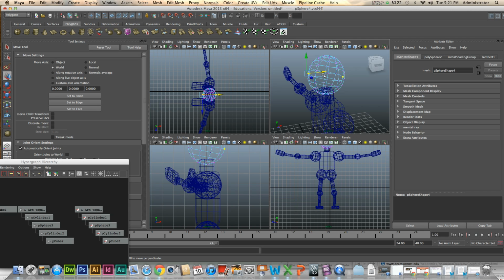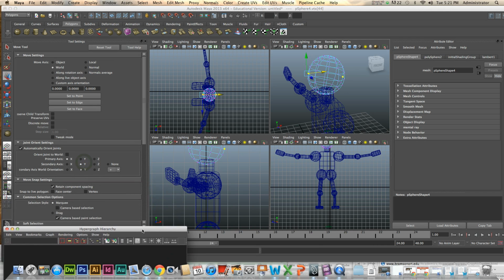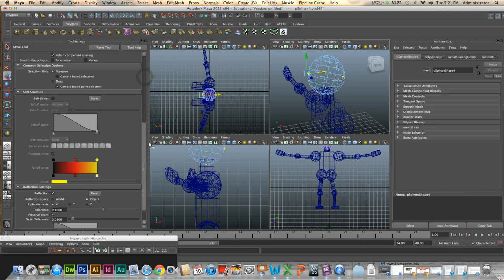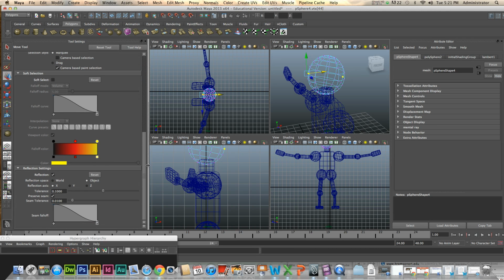And this way you can see that this point is selected. But I'm here to tell you that the reason why this point is selected is not because by mistake I grabbed both of these points. It's because my move tool has something called mirroring on it. And what I'm going to show you today is if this happens to you, double click on your move tool and scroll down, and you're going to see that reflection, okay, is on.